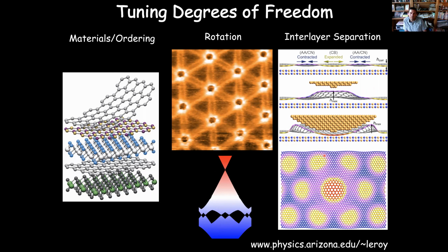Right, because the overlap is too strong between the two layers, the tunneling is too strong between the two layers. It's just not sensitive to the gate. The gate just puts charge on the layers, but that doesn't modulate the tunneling between them in any appreciable way.